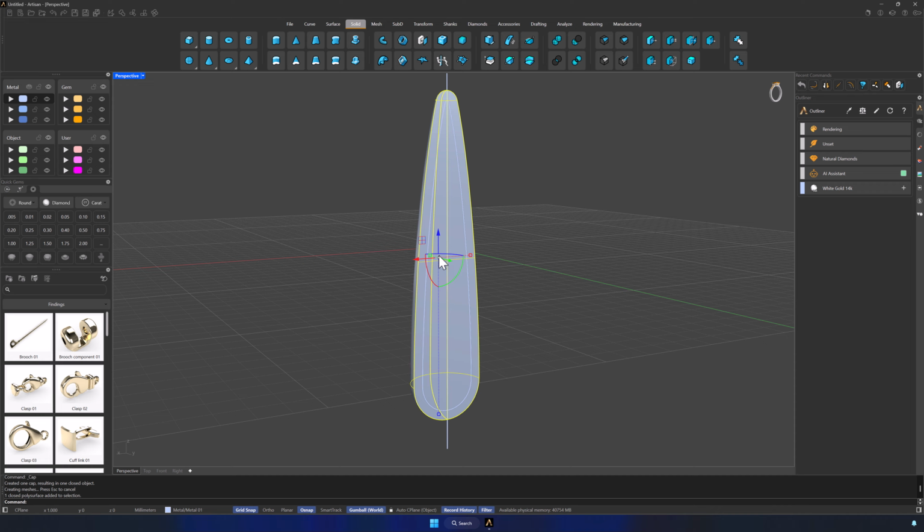Use Extract Surface to remove the cap we just created. In the command bar, I will make sure the copy option is set to No, so it extracts the original surface. Next, I will select the extracted surface and also the internal surface. I will click on Trim and cut away the inner part of the extracted surface, keeping the edges intact.